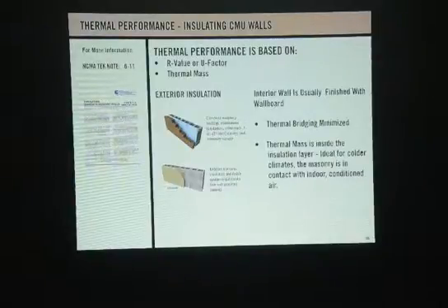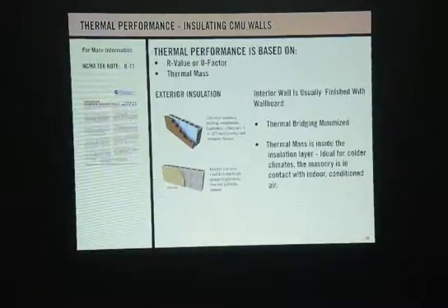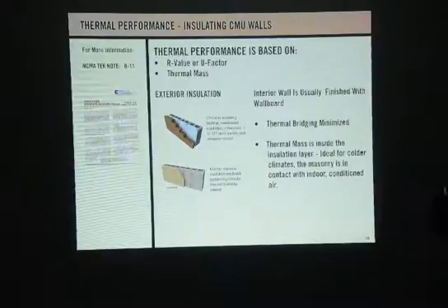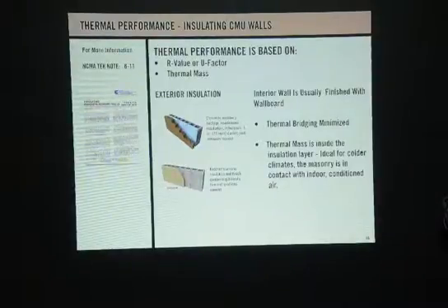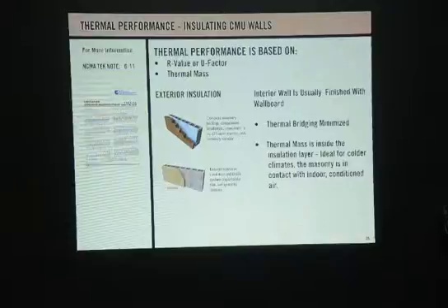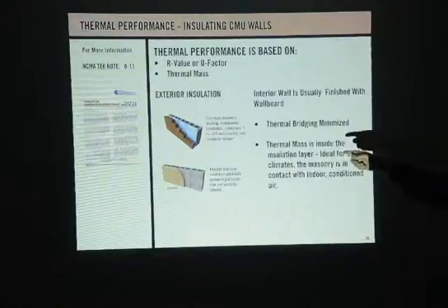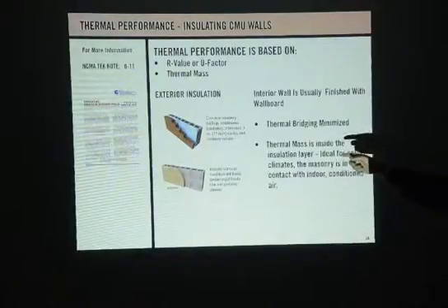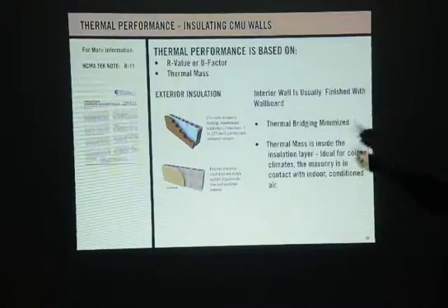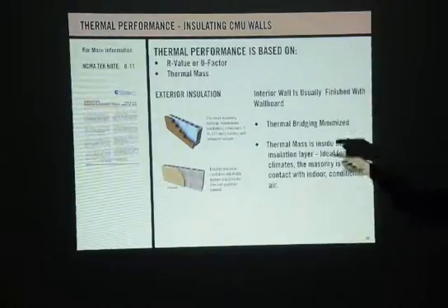Now, is the 1 web more expensive than the 2? Yes, it's about 30% more expensive in material, but the nice thing about it is it's produced at the factory. So that means the mason doesn't have to do anything, except for that photo that we saw with the Las Colinas detention center, because there is another one in Otay Mesa too, in San Diego.